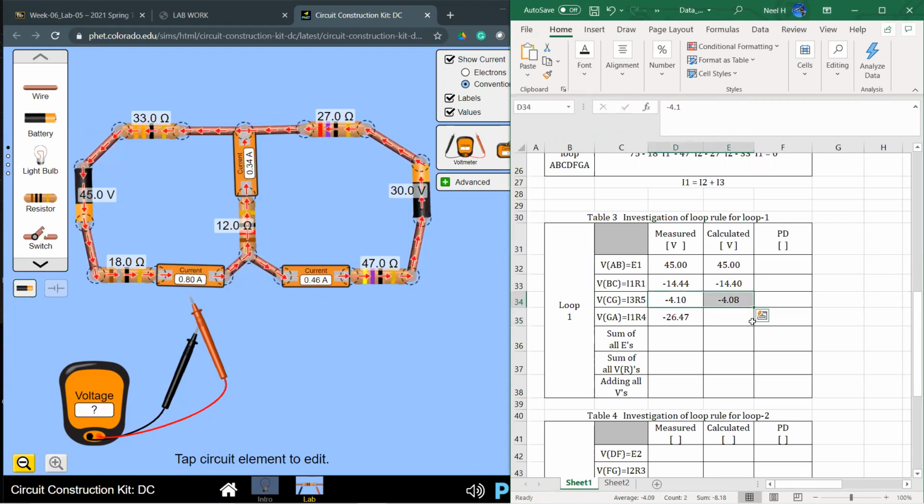There's a very small difference, that's just the rounding error, otherwise it's about the same answer. And we'll do the same for R4, equal sign, and according to the sign rule it should be negative. Multiply by current I1 again, 0.8, multiply by resistor R3, about the same. So that confirms Ohm's law is still valid per given item in the circuit.